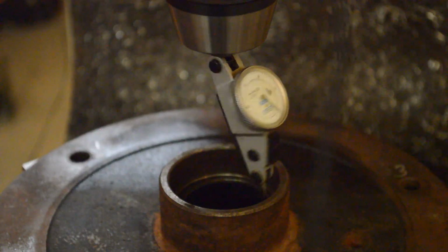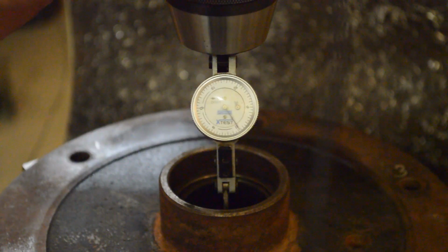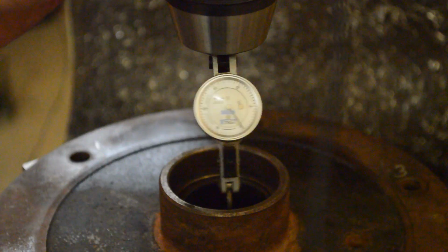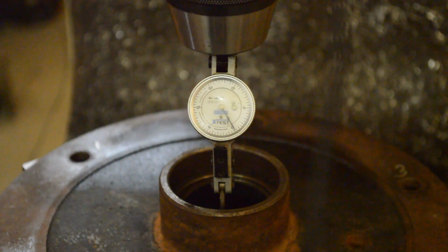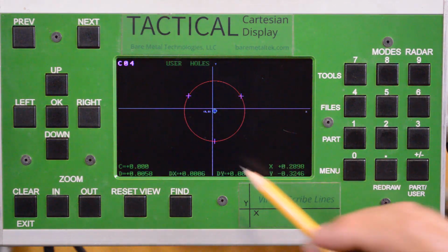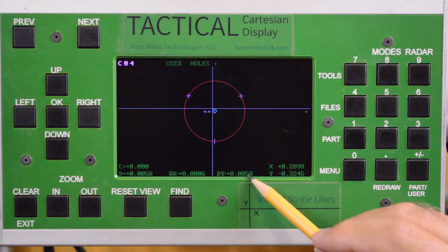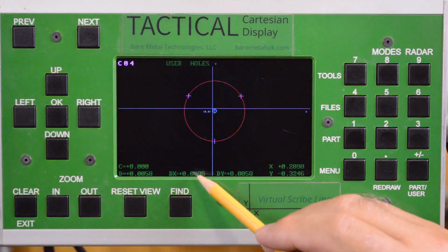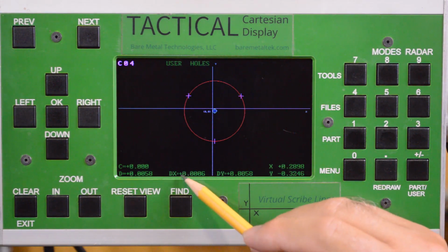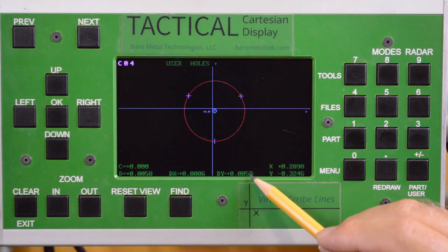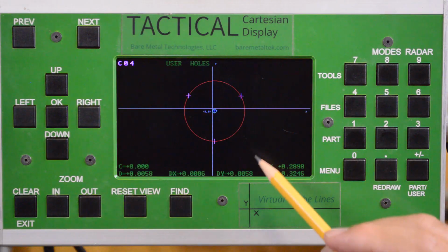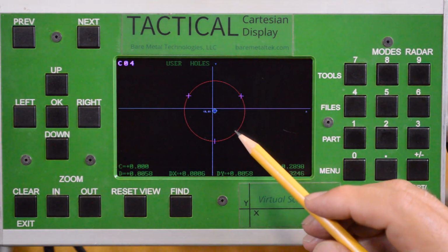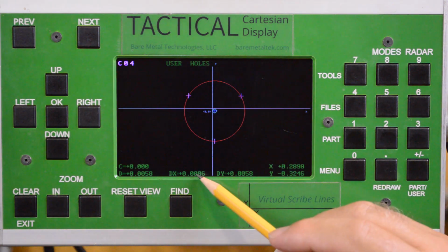Okay, so I've navigated the spindle to the center of circle 4, but then when I got there, I had to tweak X and Y around a little bit to get an acceptable TIR on the bore. Now look at the dx and dy on radar. They've been tweaked a little bit. I had to move the machine a little bit off of 0, 0 in order to get a good indicator reading, about 6/10 in x and almost 6/1000 in y. That tells me that the bore in the middle of that flange was never exactly on center with the bolt hole circle. But remember, in this mock example, we wouldn't have had that bore to indicate at all. We would never have learned this.